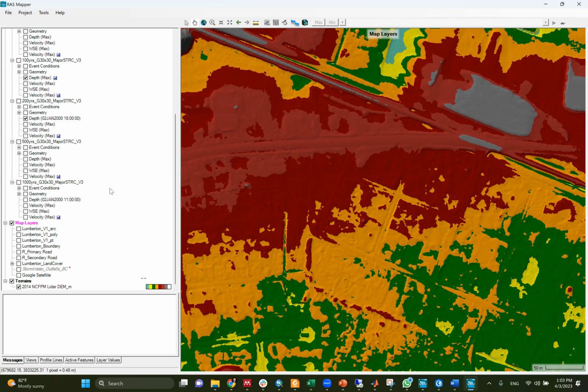Maybe it can work. I believe maybe 50 or 60. No, it can't, because we cannot exceed 1 million mesh. If you exceed 1 million elements, it might crash. So this is just a heads up about if we try to build the building model. So we will take it step by step in the project.